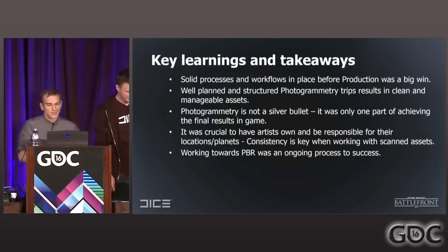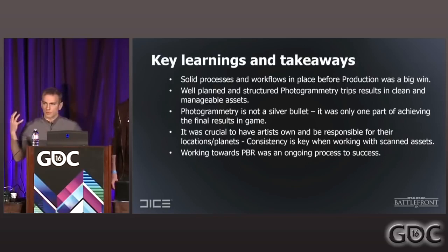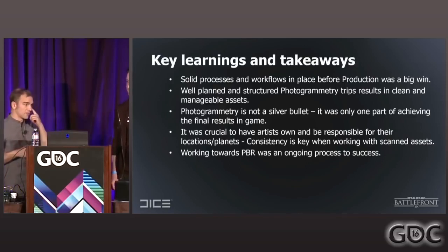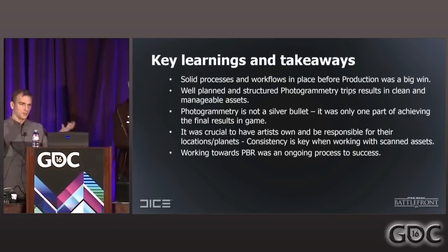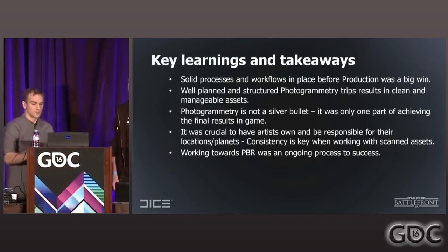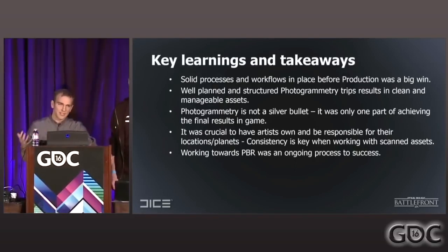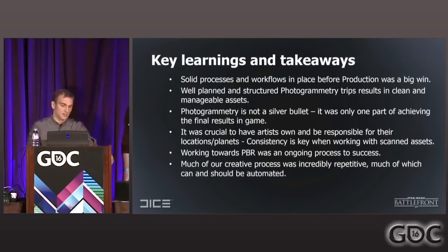Working towards PBR was an ongoing process, as I mentioned. Actually, there's a quick anecdote I meant to give during the slide about making sure everyone was maintaining the standards of PBR. On Endor, we had a case where all the values were about 30% brighter than they should be. But it's really hard to tell because the exposure would compensate down for that increased intensity. As a result, everything in that level was unexpectedly dark, and we couldn't figure out why for the longest time. We ended up having to do a PIX capture, read the values, and see that we were about 20–30% brighter than we should have been. It emphasized that you constantly have to be checking your values.